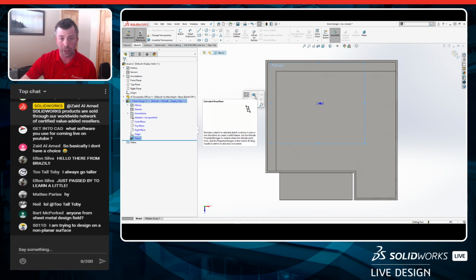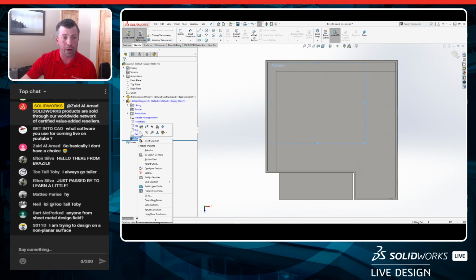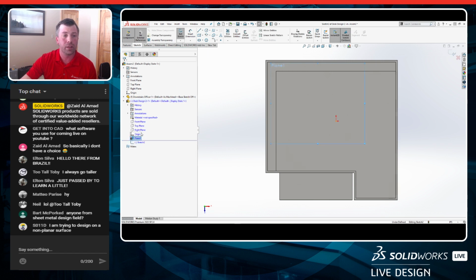So right now, I could create an extrude, a new plane, and so on. But what I'll do is reference that plane I just created, and we'll generate out a new sketch. The S key now becomes relative to sketch tools that I use often. And you can customize this as well. Just right click and hit customize and drag in any other features or sketch items that you use. You can just pull that into your S key dialog box, and it's right there.